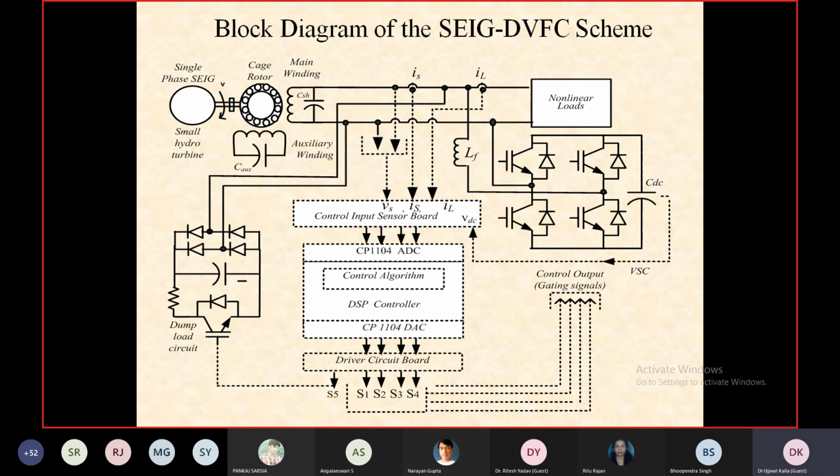If the shape of the voltage changes, then this indirect control will not work. Otherwise, the indirect control is really excellent. Very simple. And it has less calculation burden. If the calculation burden of the control algorithm is reduced, the cost of the controller will be reduced.